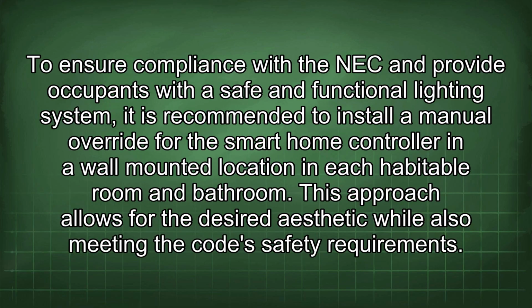To ensure compliance with the NEC and provide occupants with a safe and functional lighting system, it is recommended to install a manual override for the smart home controller in a wall-mounted location in each habitable room and bathroom. This approach allows for the desired aesthetic while also meeting the code's safety requirements.